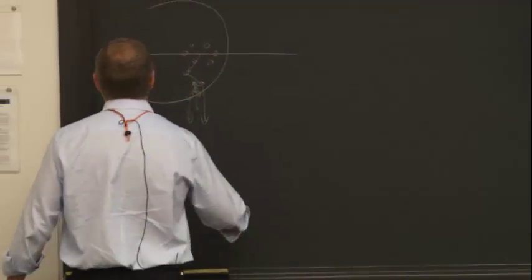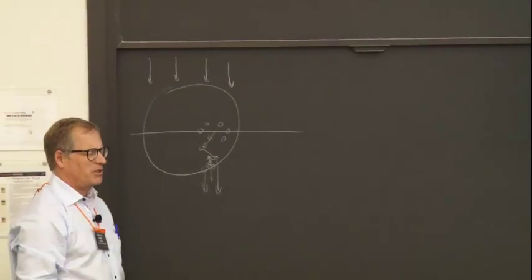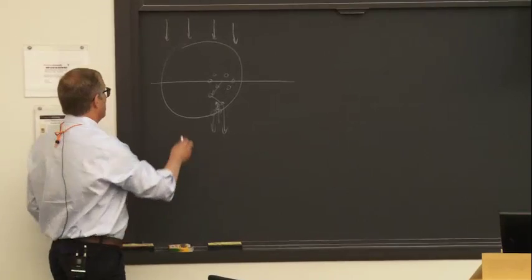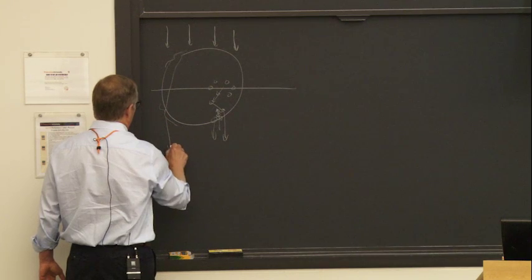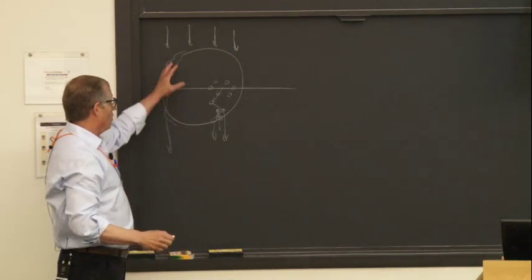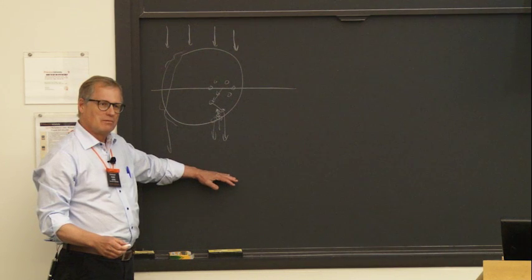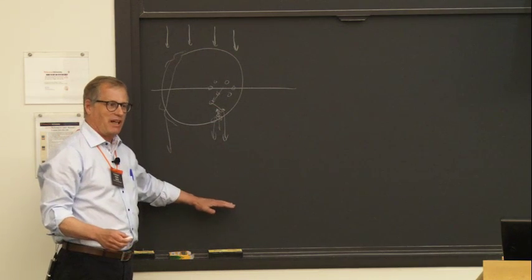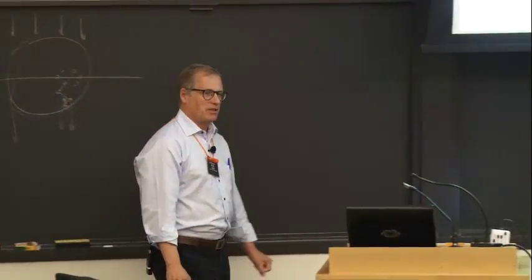when you do Schlieren imaging, you're coming through this way, right? And Schlieren is refraction, so anytime you have an index gradient, it will start to steer light. So there might be an index gradient right here that steered some light, and then there might be an index gradient here that'll steer it that way, right? And these things can move around relative to each other. When you get an image, all these things are piled on top of each other. So what really moved? You don't really know, because the input face and the output face are all sort of added up together. So you can't really do image correlation velocimetry on a Schlieren image.